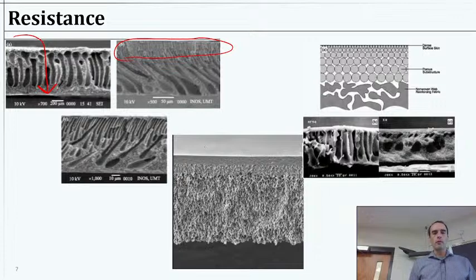Okay, a couple more examples. Even this one down here, you see is a really smooth, flat surface, really, really thin. You can't even really see pores in it, but you can imagine water might be able to squeeze through the cracks, right? So maybe these ones on the left are more like microfiltration, ultrafiltration, and here we might be getting down to sort of nanofiltration. So you can see how that's going to resist the flow of water, and that's what it really looks like.